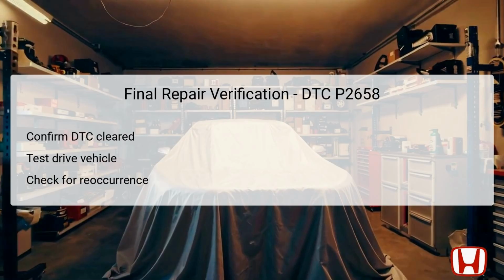After addressing the issues identified during troubleshooting, it's essential to verify that repairs have been successful. Start by ensuring that the DTC has been cleared using the HDS. Once confirmed, a test drive of the vehicle is necessary to allow the VTEC system to engage and operate under real-world conditions. During this test drive, monitor for any abnormal engine behavior or warning lights that might indicate a persistent issue. Finally, after the drive, check the system again with the HDS to ensure that DTC P2658 does not reappear.